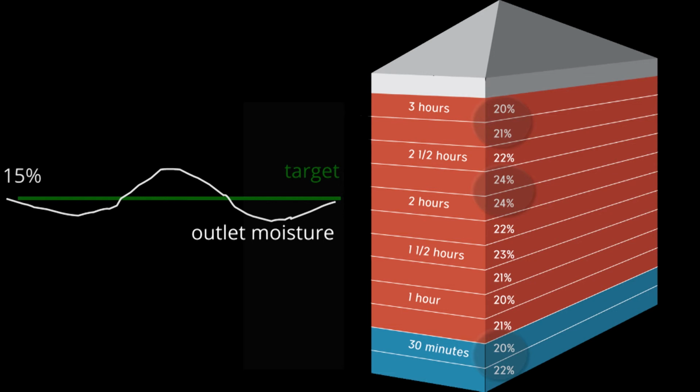This means that the grain ahead of it will overdry a bit, and the grain after it will overdry a bit. But it also means that the 24% grain will be drier too. So here you may end up with some 14.5% grain, then some 15.5% grain, and then some 14.5% grain, but with an average around 15%, which was your target.